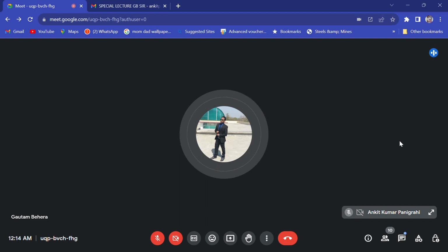Any other difference? What is the limitation of pellets? The limitation of pellets is that pellets stick with one another. These are balls, and they will stick with one another. That's the problem during processing. If you add flux, there will be more sticking. That is another problem, right? You cannot make fluxed pellets, that's why. But you can make fluxed sinter easily.